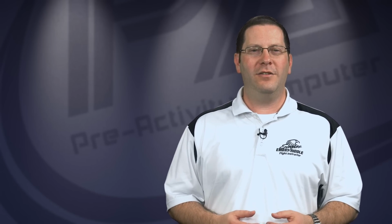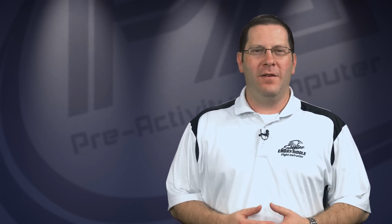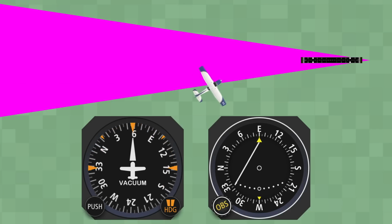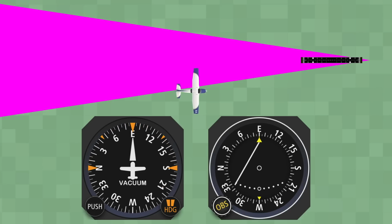The AIM states that you should not use the back course for an approach unless a back course approach is published for that runway. For pilots flying back course approaches using a CDI that is independent from their heading instrument, you must be aware of reverse sensing when flying towards the airport. This occurs because the course deviation indicator is not aware of your aircraft's heading or position relative to the fix.